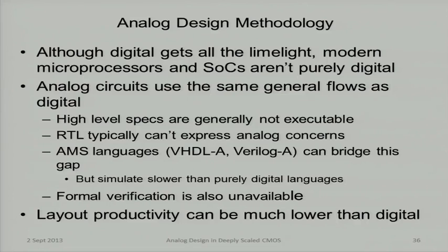RTL is, I don't have a good structural level equivalent for my analog circuits. And then I get down to the schematic level. And I don't have formal verification, but I do have behavioral descriptions I can utilize in AHDL or Verilog-A or one of these. And another just side note, the layout productivity is quite low. So if we could do something about that, that would be great.